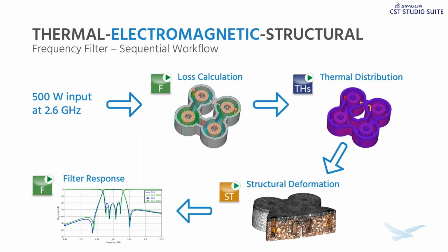And then because of the shape change, we have to go back and do another electromagnetic analysis to figure out what the filter response is going to be. And this one, we actually saw that as it heats up, the frequency is going to shift down just a little bit. And so it's important to incorporate all of those.